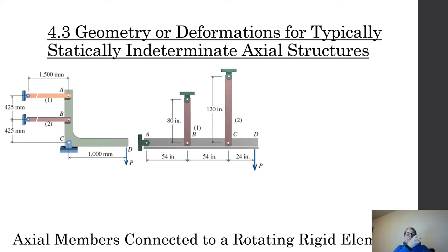it's not so easy. If I sum forces in the X direction, I have 3 unknowns. If I sum forces in the y direction, that's great. I can get the y component of my pin at C. But I have 3 unknown x's. If I sum the moments about C, I still have unknown 2 and unknown 1. So we're back to it's 1 degree indeterminate.